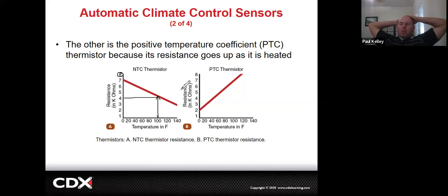If your evaporator core temperature sensor is reading, let's say 30, when it's actually 60, it's going to think it's blowing cold air, but the air is going to be ambient, more or less. It's not going to be that cold. And you could recharge it. You could do all this diagnosis. It actually may or may not set a code.